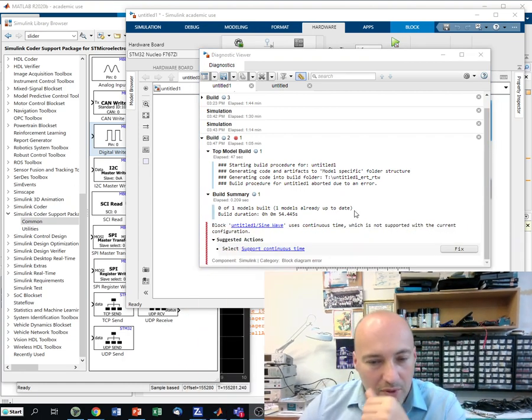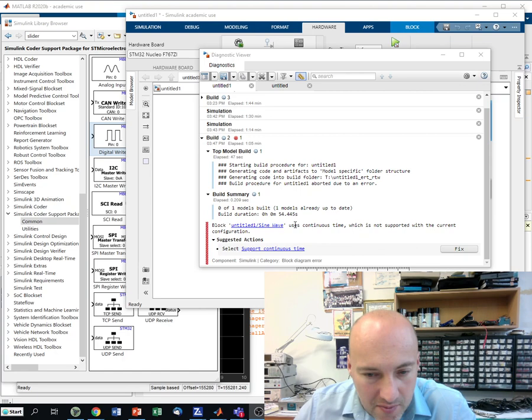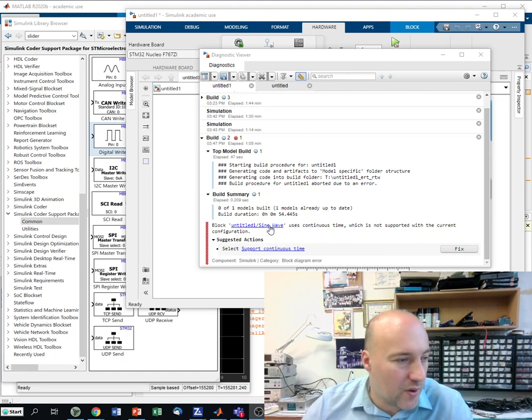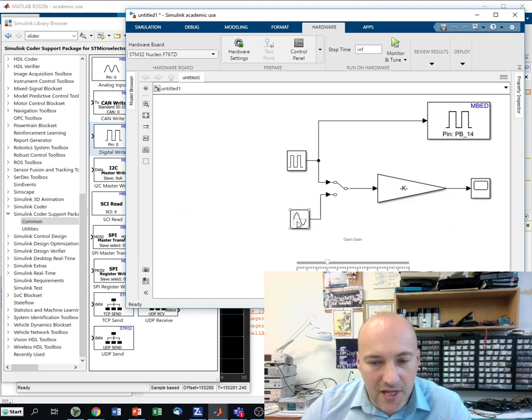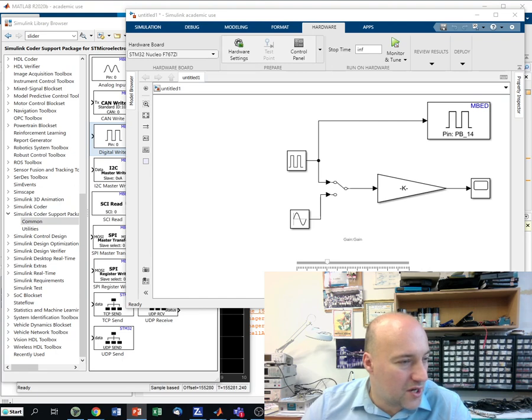And the problem is that I have now used continuous time in my block for sine wave. So the problem is here, and we'll have later the same problem here. I forgot to change it. We need to use discrete time.